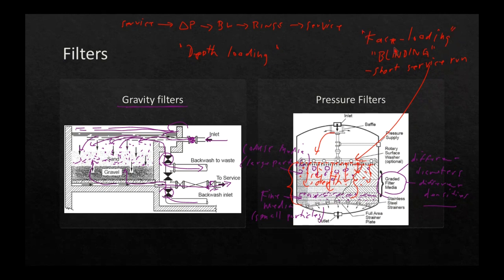And you can see how we're basically using the filter media more effectively by having those particles actually penetrate into the bed. So depth loading is desirable. Okay, it's more gooder. It's better. And it leads to a long service run.